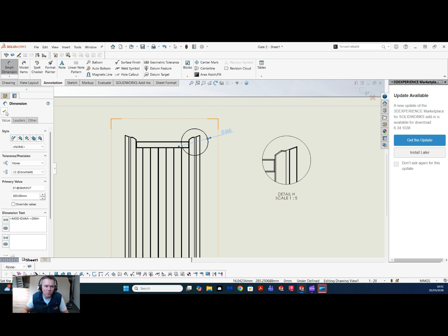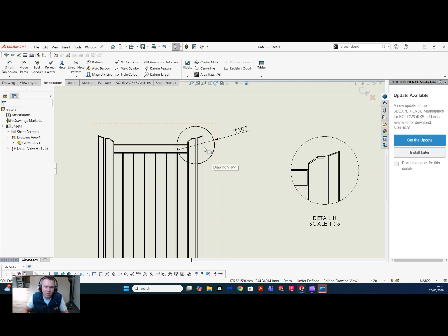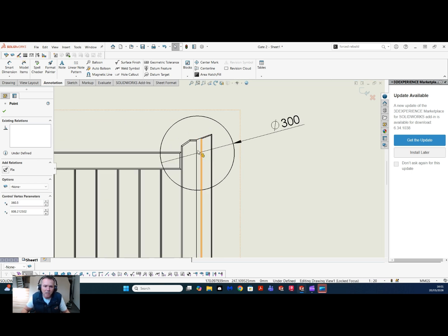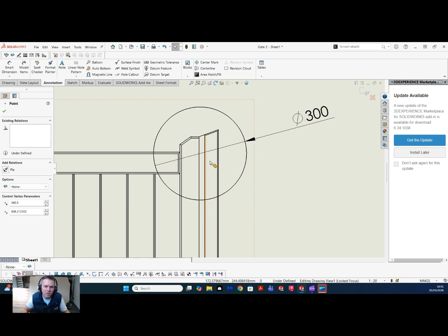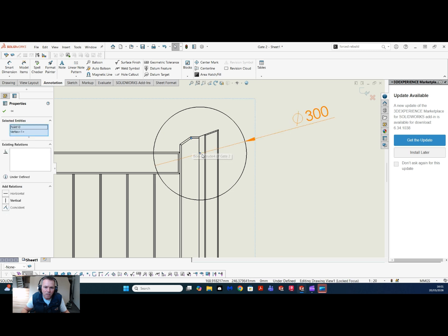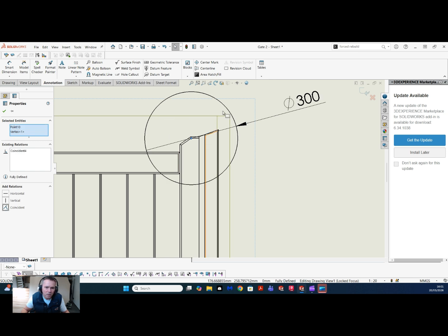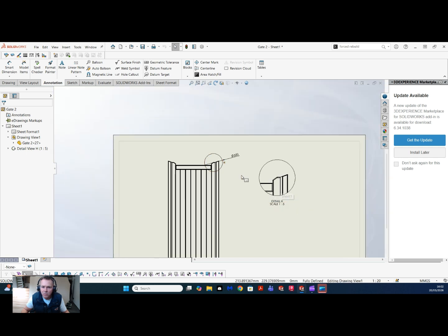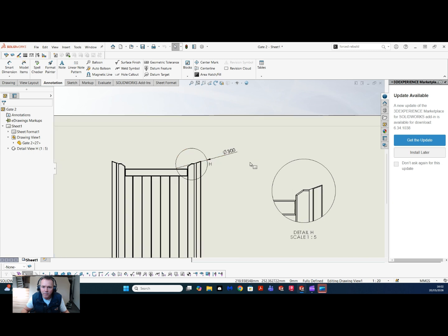And we could also maybe constrain the center of it. You can already see it's actually already created a coincident relationship to wherever it was. Let's just remove that, because wherever I clicked it on, it must have picked up that line and then made it coincident to it. So we can highlight, bring up the center circle, and maybe go to shift and find another point to click it to, and then like you would when you're doing sketches in models, just go coincident. There we go, we can move it over there and exit the sketch, and we've got some control over that.